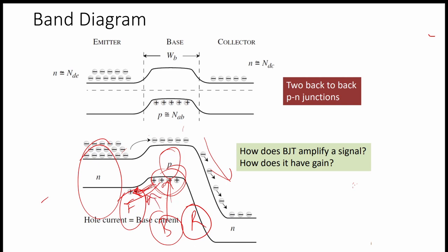Okay, reduce this current, and we can also play with the depletion region width in this region. As we apply the reverse bias here, the depletion region width gets increased. Initially this was the base region, which is not depleted, the neutral base region. But when we apply a high reverse bias, this base region will be shrunk.